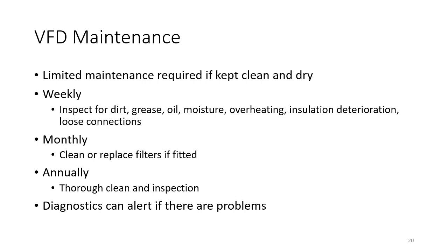It could be those filters are actually on the enclosure. If the VFD is inside an enclosure, you don't have fans on the VFD itself, you would actually have those fans on the enclosure. And then annually, you might want to do a thorough clean and inspection of the VFD. For example, you might want to just use some sort of air pressure to clean the vanes of the heat sinks just to make sure they're not clogged up with material. But again, if they're kept clean and dry, that should be a minimal requirement for that. The great thing about a VFD is there are diagnostics.